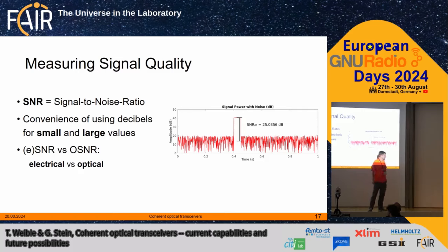Getting to the next slide, signal quality is another way to measure it. That is the view of an electrical engineer. We like to use dB because it is based on decibel, logarithmic. Log A times B is the same as log A plus log B, and if you apply an amplification of the signal, you can just add it.